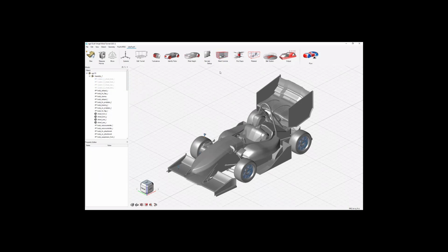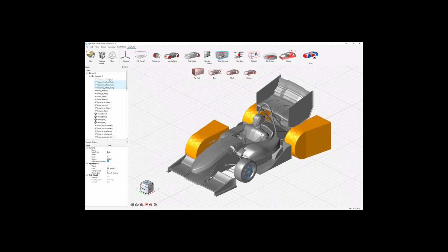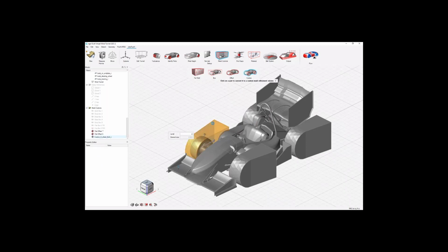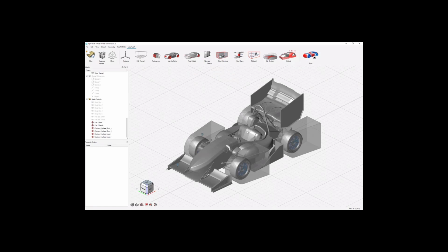we go the same route that we just took, we can choose mesh controls and maybe first show them. Then choose mesh controls again, click on custom, and then click on those custom refinement levels. We want those ones to also have refinement level 6. Okay, and that's it. They're already named correctly, so they have the 6 in the name. So now we are finished with identifying the refinement zones. So let's hide them again for visibility.